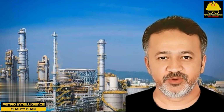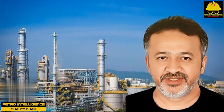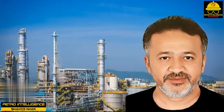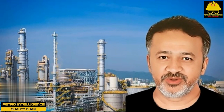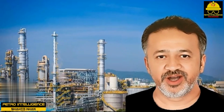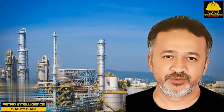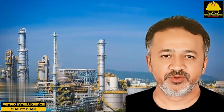Steam stripping hydrocarbons: 50%. I don't have a solid basis for any of the above parameters. The values quoted are mostly what I've seen other designers use. Large negative variations from these parameters are rarely due to any calculation problems. Almost always, the problem is bad tray design or sloppy installation, or both.